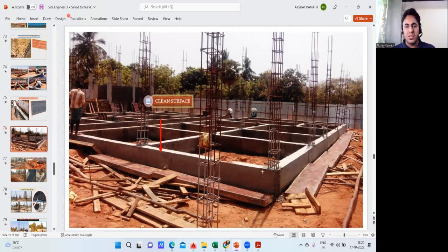So we know that this length we took from column outer to column outer. Length we took. Breadth we will take now. And if I multiply this by the depth, I'll get the concrete quantity here. Agree with me? This is the breadth of your beam. This column outer to column outer is the length of your beam. And if I multiply this by the depth, I'll get the total volume of concrete that is required in the plinth beam. Okay, maybe PB1, PB2, PB3, or GB1, GB2, GB3.